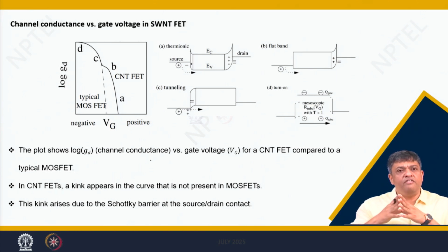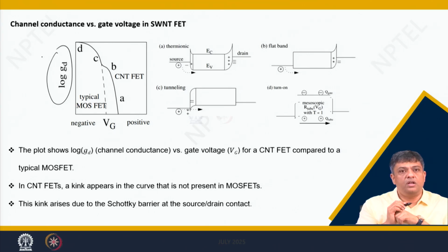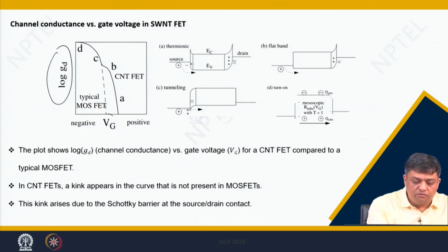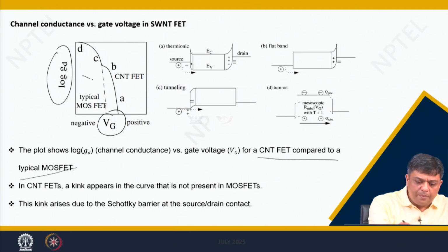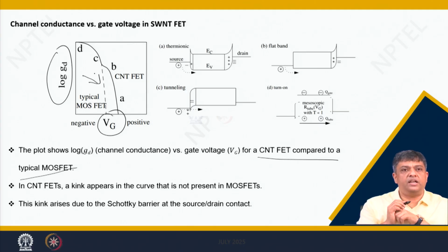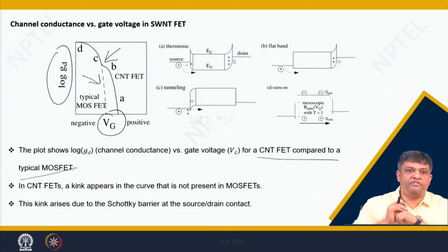You can get various configurations and you can have plots of, let us say, log of channel conductance versus gate voltage, and you will find that if you compare with a typical MOSFET type structure, you can see that there is a significant change.